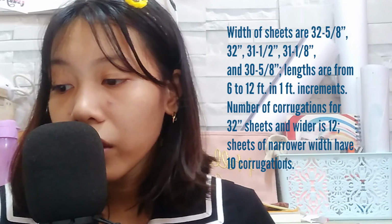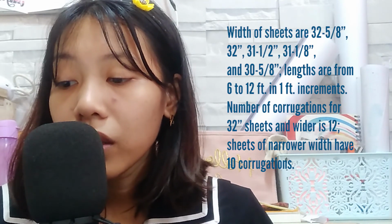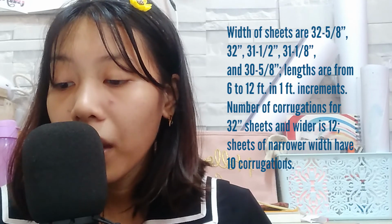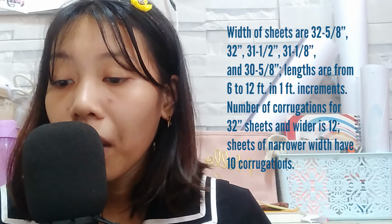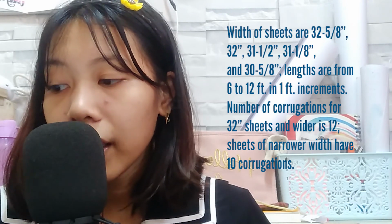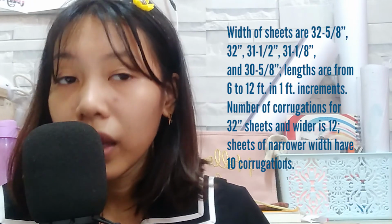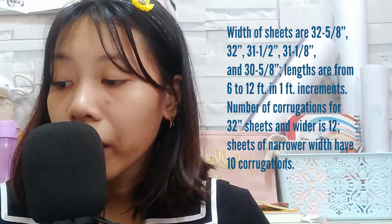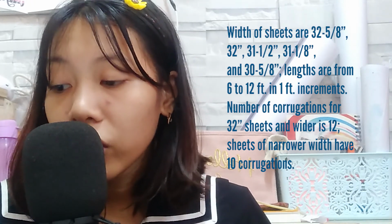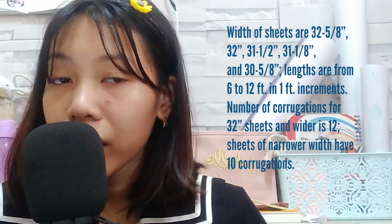Widths of sheets are 32-5/8 inches, 32 inches, 31-1/2 inches, 31-1/8 inches, and 30-5/8 inches. Lengths are from 6 to 12 feet in 1 foot increments. Number of corrugations of 32-inch sheets and wider is 12, while narrower sheets have 10 corrugations. That's all, thank you!